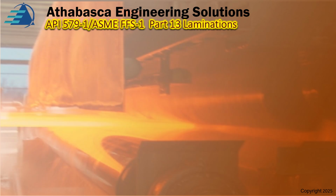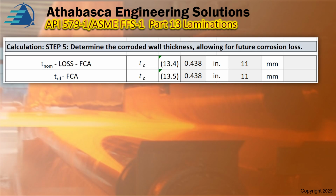Kind of interesting. I recommend going to step 5 first. In the 2020 edition, they've moved this procedure to step 5, even though in steps 2 and 3 you need this value. So basically, we're just adjusting for the corrosion allowance and the future corrosion allowance and so on. So just be aware of that.